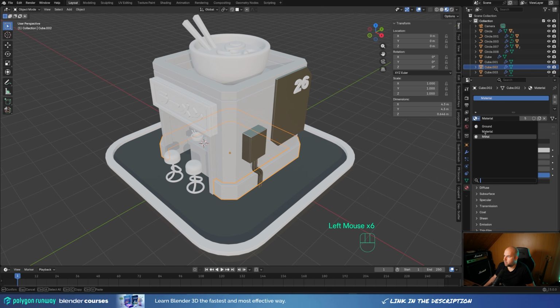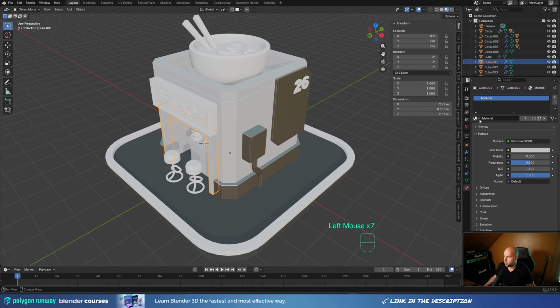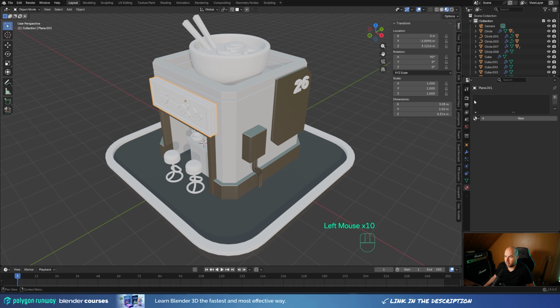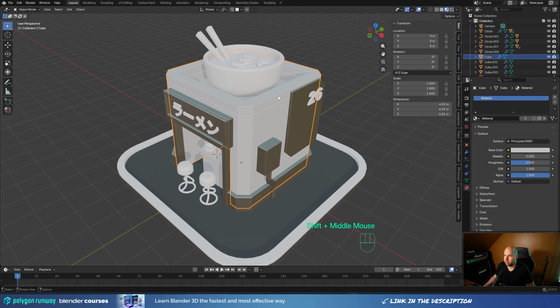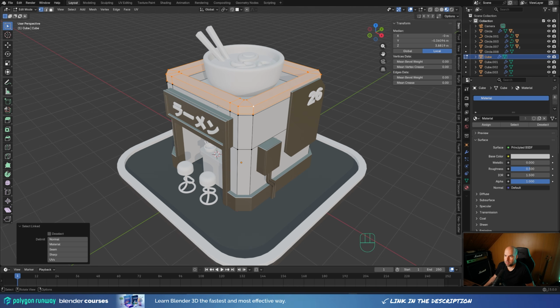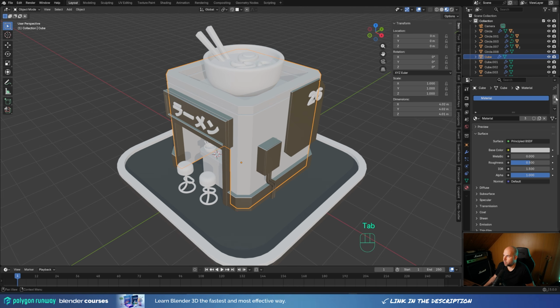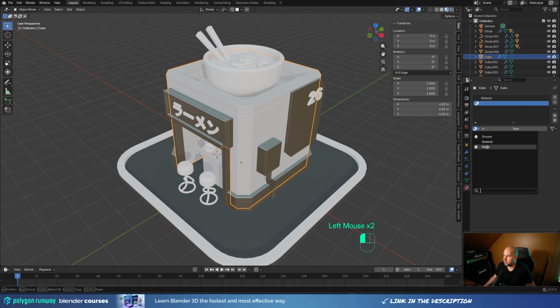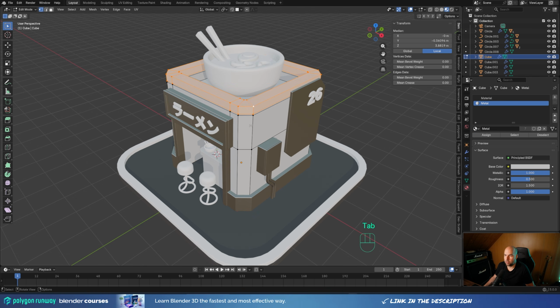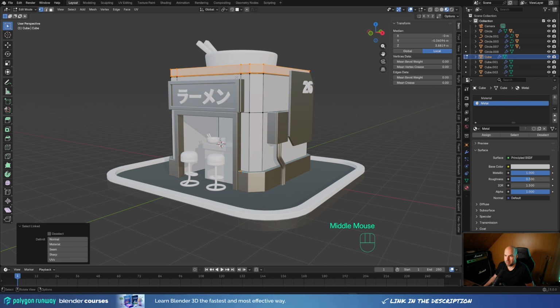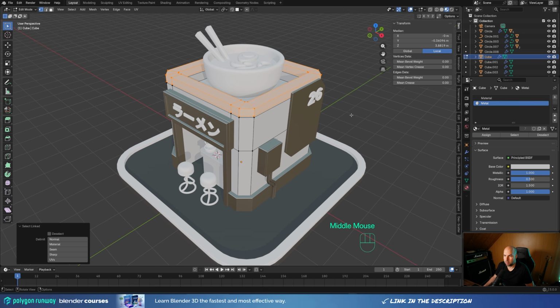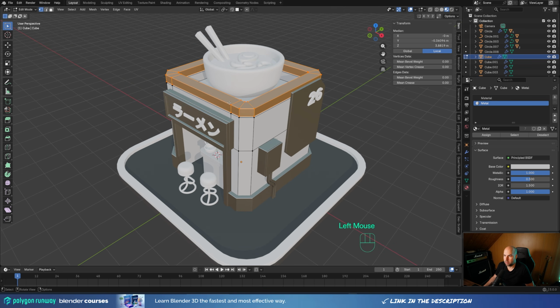So for example, here on the frame around the building, I think that's a great place, and for the sign as well. And now here I want to apply the same metal material, but we have this as a single object, so we have two options. We either detach this geometry or we use another material slot. So in the object mode, you can just hit plus here and apply a different material, but now you need to go into the edit mode. And if you don't have it selected, you can just hover over one part and hit L, and whatever is linked and disconnected from the rest of the mesh will get selected. And now you can just hit assign, and that will assign the new material to your object.